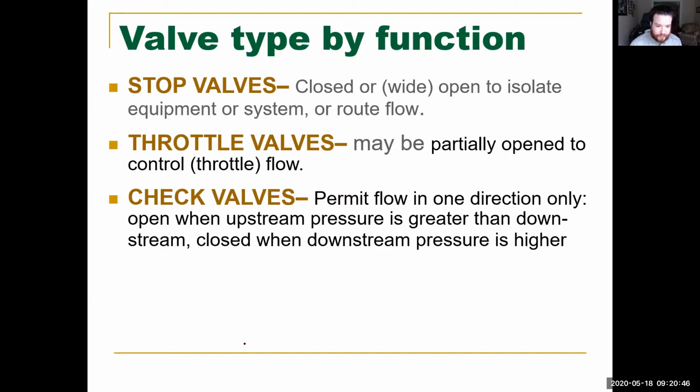All right. Again, you can have a check valve in a spot where, if you have a tank here and you have a pump that's sitting on the edge of the tank, pumping upstream and trying to go, let's say, upstairs, to the second floor, you would utilize a check valve here because if this pump is operating when there's fluid inside of it, what's going to happen between this spot here and this spot here?